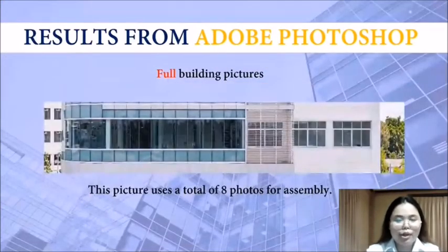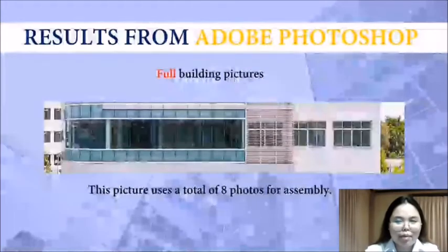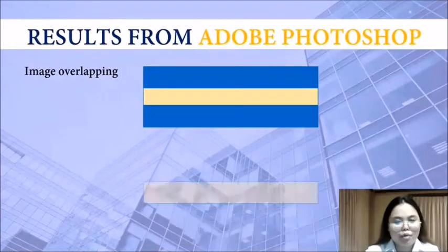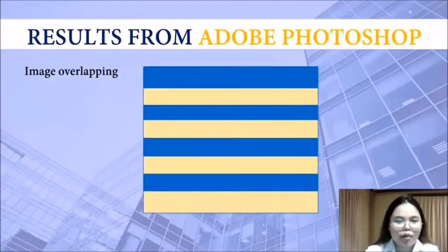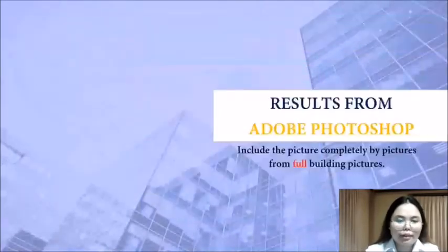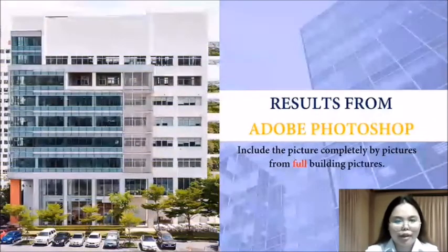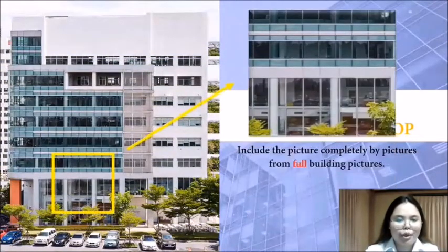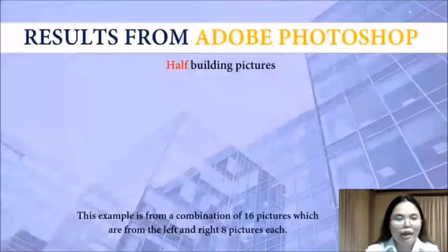In full inspection of each building section, the UAV took 8 photos from a distance of 37 meters away from the building. This is the process of the image overlapping of full inspection. The overlap of each photo is about 40 to 60% as planned. This is the result from the full inspection process. The facade had a high resolution quality, which can be inspected at normal surface directly from the zoomed-in picture.